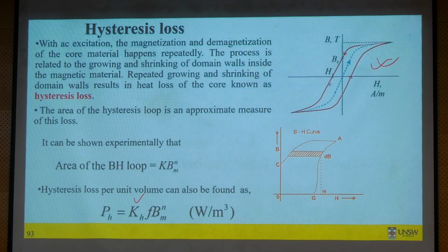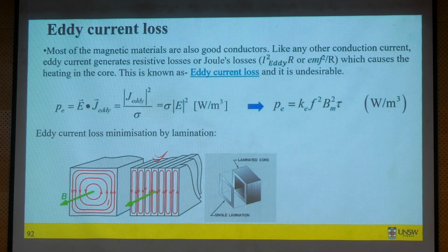Finite element analysis we can use to calculate iron loss for a PM machine. Again, it is based on a model, such as this type of equation. They just estimate these coefficients, the hysteresis loss coefficient KH and the eddy current coefficient KE. The estimation of these coefficients is again not very accurate.